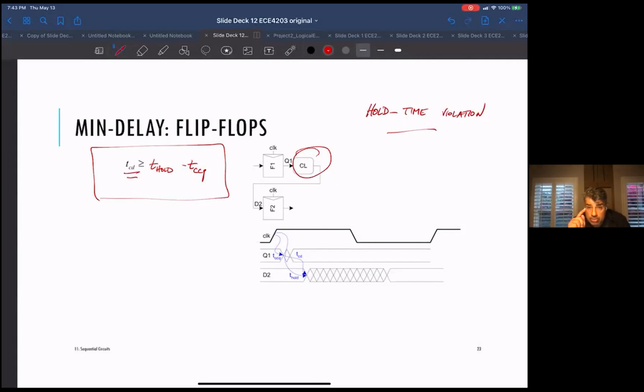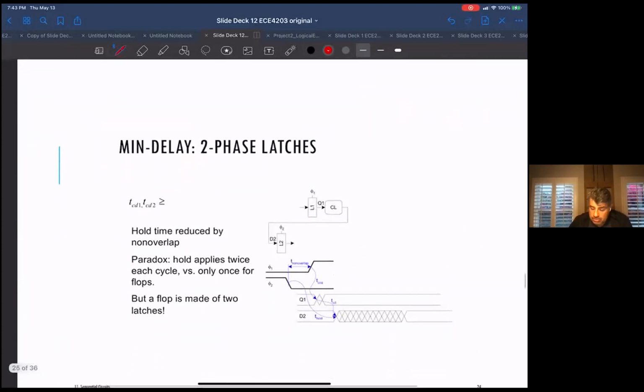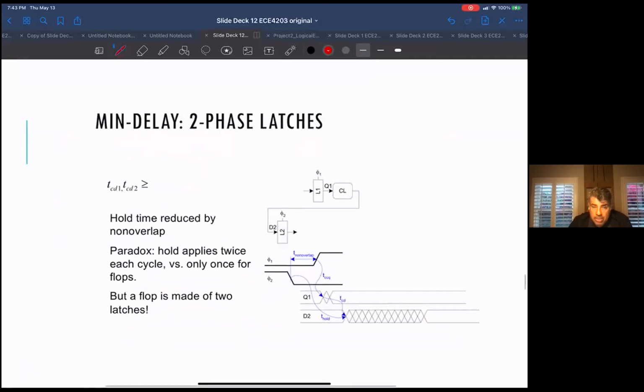The shift register means they're just going directly from one to the other. And if you screw that up, you just get a non-working chip, non-working testability, which sets you back a couple million dollars and a year.